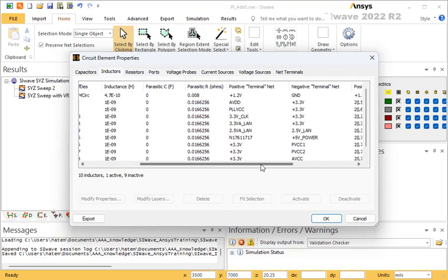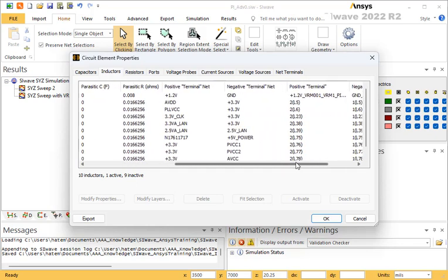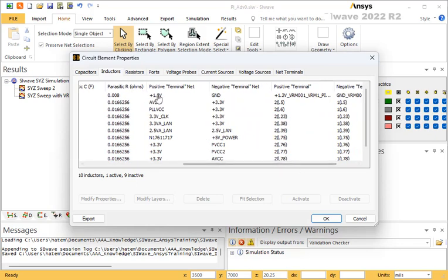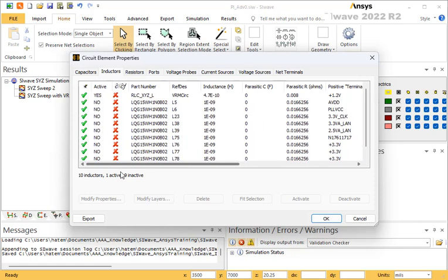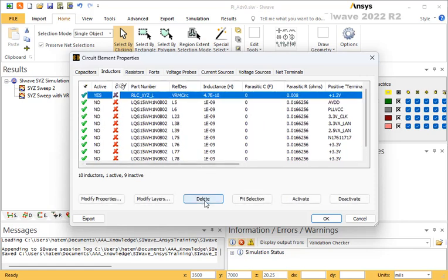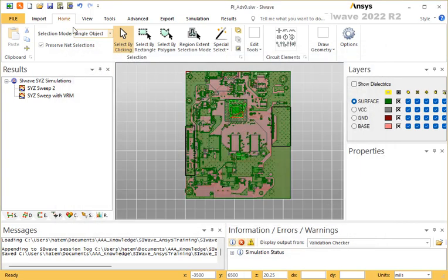And it's very important that you do that because sometimes when people generate circuits, it attaches itself to the positive, but the negative is not connected. So something went wrong during the connection, and I noticed that many times. So it's good to go back to this and check and make sure that the connection to the ground exists there. Otherwise, you need to click on this component, delete it, and repeat the connection again to make sure that it's done in the proper way. So once you do that, then you have only one other step to do.